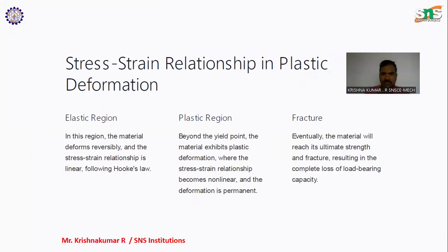Stress-strain relationship in plastic deformation. Elastic region. In this region, the material deforms reversibly and the stress-strain relationship is linear, following Hooke's law. Plastic region.